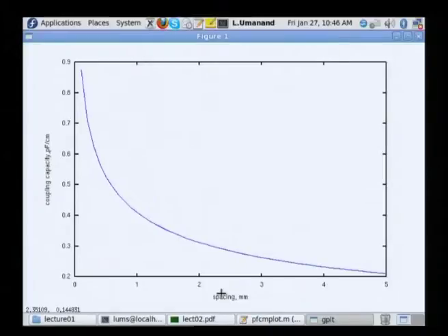Okay. Keep that in mind and try to look at this figure from that viewpoint. The capacitance per centimeter: if you take 1 centimeter length, you have this amount of capacitance, and this capacitance is decreasing as a function of spacing. Yes, the more the spacing, the smaller the value of capacitance, and that is what we expect to happen.